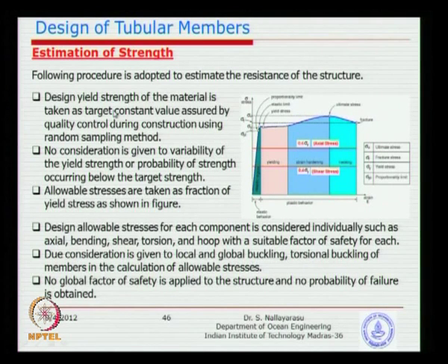How much the variation is depends on the workability of the concrete and how the concrete is made, and that means the characteristics of the concrete strength could be influenced by human interference. How you make the concrete, how you pour it, how you vibrate and compact it, and how you cure it could change the strength by a certain percentage. That means the variability of concrete in the same structure from one location to another could vary considerably, and that is why when you build structures you normally do sampling, take a cube and go to the laboratory for testing.